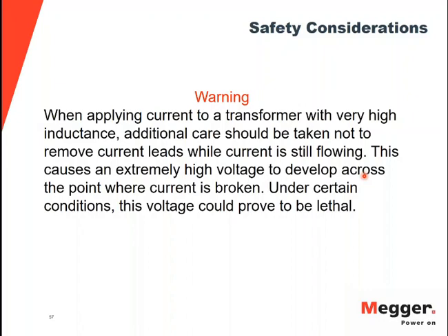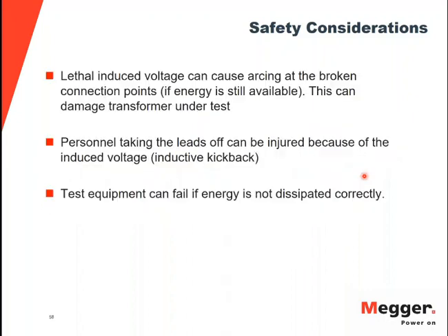So it's highly recommended to discharge the energy stored in the winding before you take the leads off. And most automated test sets do that automatically. At the end of the test, they would discharge the stored energy, so that way it is safe to take the leads off.